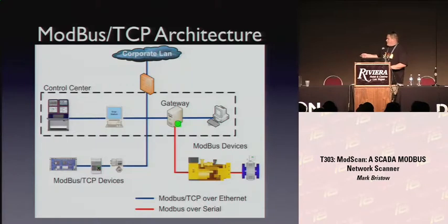And then occasionally you have your gateways that typically talk to more legacy devices, things that are high capital, like generators and transformers. They might only speak regular Modbus. You just drop a gateway in there so that you can talk to them over the regular network. From the device vendor standpoint, a lot of vendors are adding Modbus TCP directly into their products, so most of this stuff is going away. But it's definitely still out there because, like I said, they're high capital investment items. They don't turn over very fast.